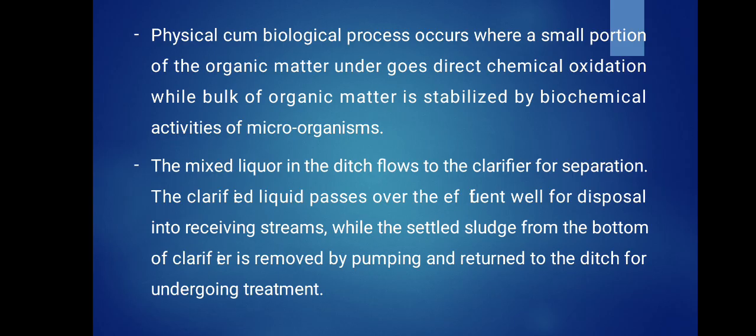The physical cum biological process occurs where a small portion of organic matter undergoes direct chemical oxidation while the bulk of organic matter is stabilized by biochemical activities of microorganisms. The mixed liquor in the ditch flows to the clarifier for separation.